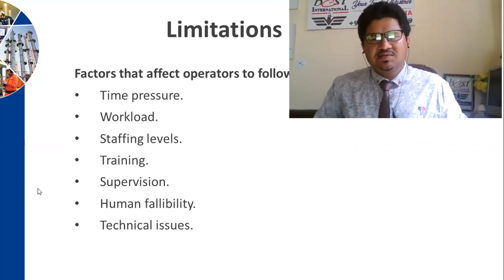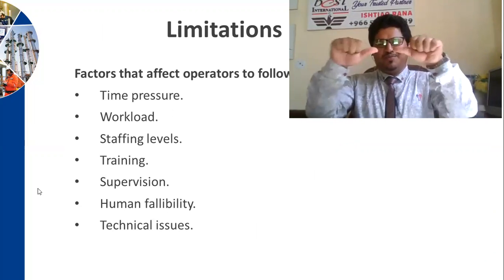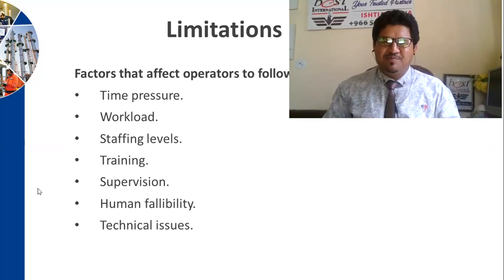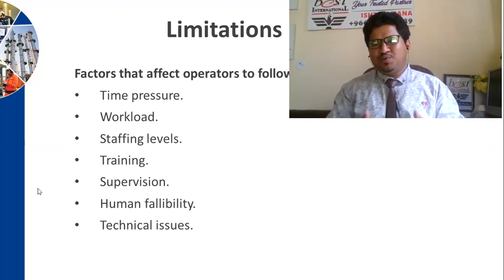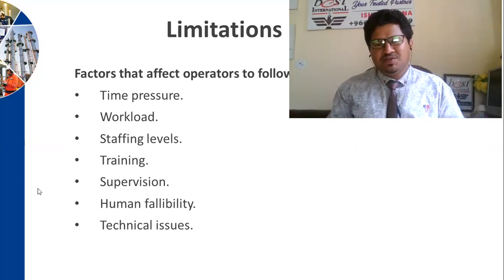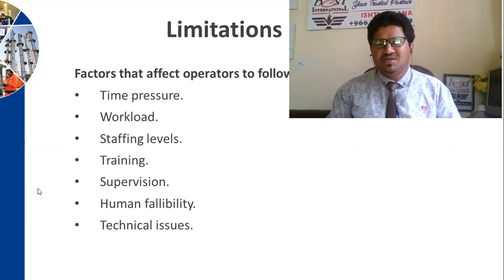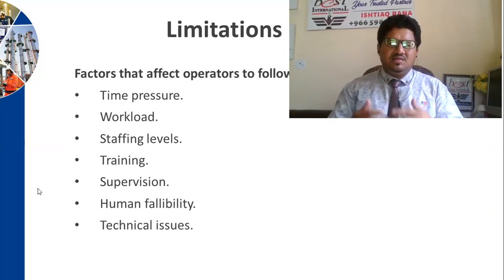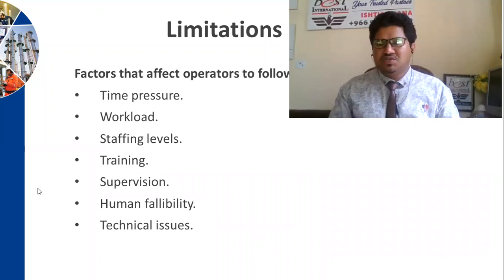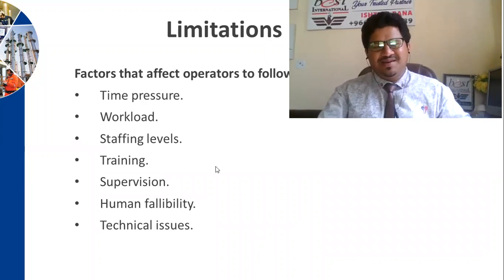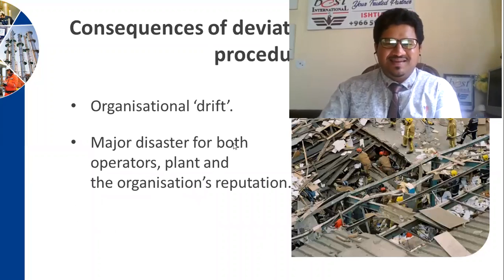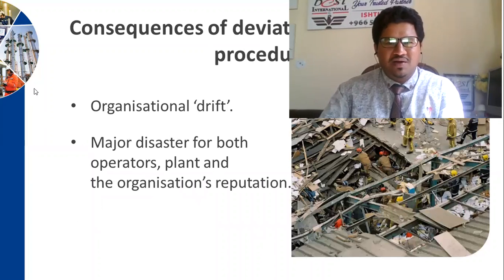In one company, as a safety auditor, what I noted was they put tape on the sensor, and I asked the machine operator, why did you place tape on the sensor? He mentioned the production manager needs just production and there is no time to stop the machine for maintenance. And this is what was guided by the maintenance team, to put tape on the sensor so the machine will not stop. So this is what sometimes happens on the ground.